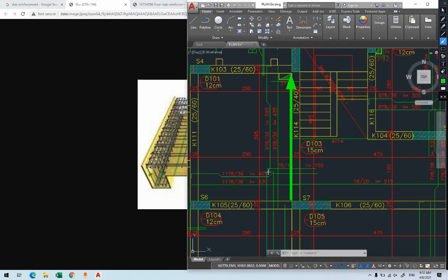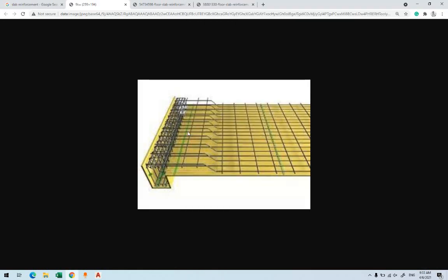You will first put these bend bars, and then in between them, how many bend bars you have, starting, for example, if you put 1 here, or maybe you will start the bend bar from where? You may start the bend bar from here. The bend bar may start from here. So you will see how many bend bars you have there, which you already know, 11 bend bars. If you don't know this one, then you can calculate this one comes in between them, which will be 9 of them. So this is the easiest way to think of it, like this. It comes in between them.